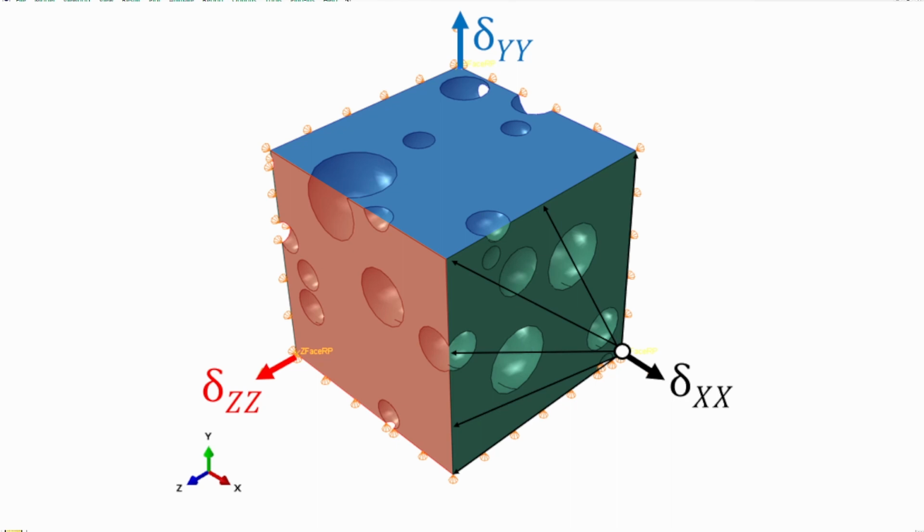I choose to do this because I want to manage the way that I extract my stress and strain data from my system. I want to extract forces that I'm going to then divide by an area to create my stress and strain data. And this is really important for a system like this because you have a lot of elements in the system, and so if you are tracking it by element consideration alone, there will be a lot of variables and you'll probably run out of memory and it will be difficult to do. So this is the way that I'm going to do it, so that in the end I'm going to be tracking only the reaction forces and displacement of the corner node. We'll speak about that in a moment.